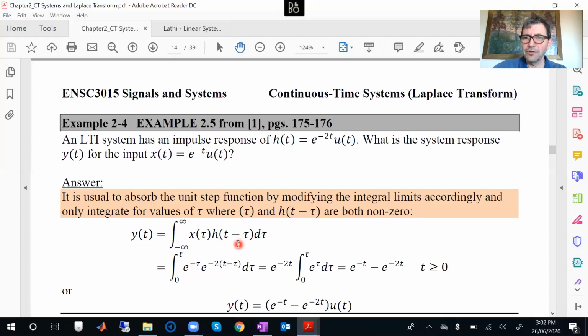Here's how you handle the unit step. And in this context, this is the only way you should really handle it. If you look at this and you understand what this is telling you, it's telling you that x only exists for positive values of t. The unit step is acting as a switch. And if you think of it as a switch, it makes your life a whole lot easier. So that means x of t is equal to e to the minus t for positive t.